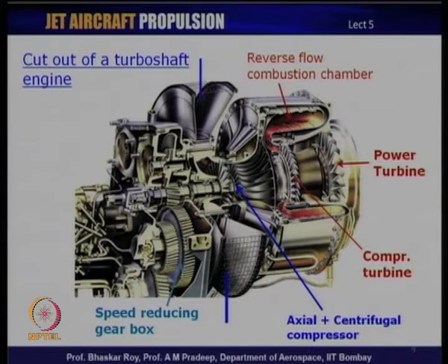Now, the gearbox is a heavy element, and hence it adds substantially to the weight of the whole engine system, and as a result a typical turboshaft is likely to be rather heavy. And that is also another very good reason why the turboshaft engine designers try to make the basic engine as compact and as light as possible, because it has to make way for the gearbox, which is an absolutely essential element in the turboshaft operation.